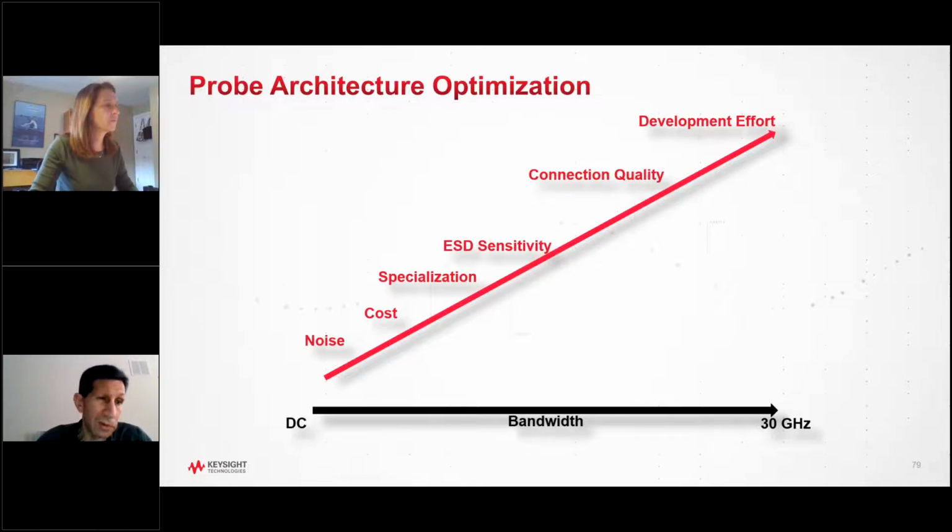Now, we generally include passive probes, which we'll get to in a minute, with the cost of an oscilloscope. But if you need higher performance probes, you'll have to pay extra. Whatever probe you use is always going to add noise to the oscilloscope, so if you have a very low noise application, again, if you can get away with direct connecting via cable, you're generally better off.